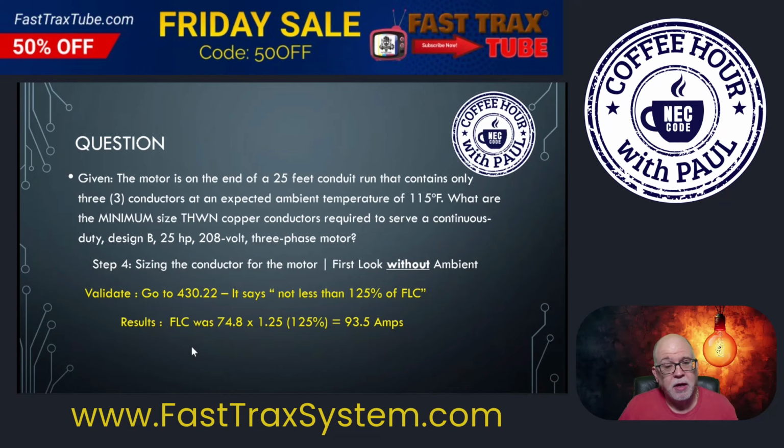All right, so if you remember, it was 74.8. That was our FLC, and we're going to multiply that by 125% because that's what it tells us in 430.22. So I'm going to do it here just to make sure our math is right. And that gives me 93.5 amps. Okay, so I have to have a conductor that has an ampacity under the 75-degree column, because we're working with the limitation of the conductor, which is THWN. I have to have a conductor that's at least 93.5 amps.